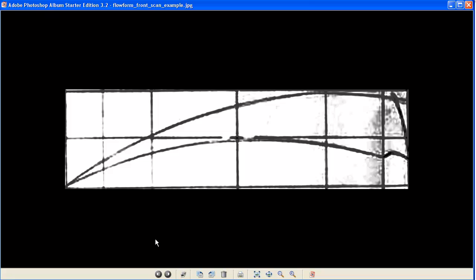To do this assignment, I have to do a little preparation ahead of time. What I have to do is get my original sketches from my Foundations project and scan them in. Here, for example, is the sketch that you just saw that was ported into Solidworks. This was scanned in and then scaled to the particular dimension that I want it to be in Photoshop. So in this case, the image, when scaled at 1:1, was 9.24 inches in this direction. So that's what I set my image size to in Photoshop.